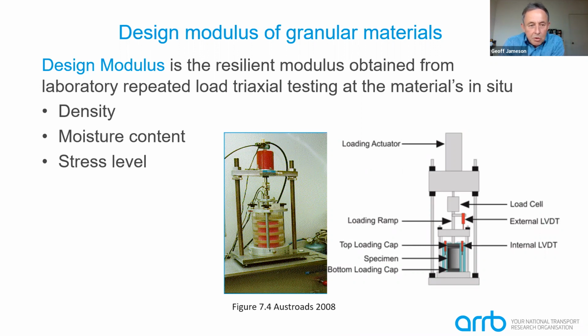For example, in Victoria, 100% of modified Proctor maximum dry density might be an appropriate density level to use. Whereas in other states, it might be some percentage, 100% say, or 102% of standard Proctor maximum dry density. So there are different standards of acceptable densities in different states. And what's the guiding thing is trying to estimate the in situ values.